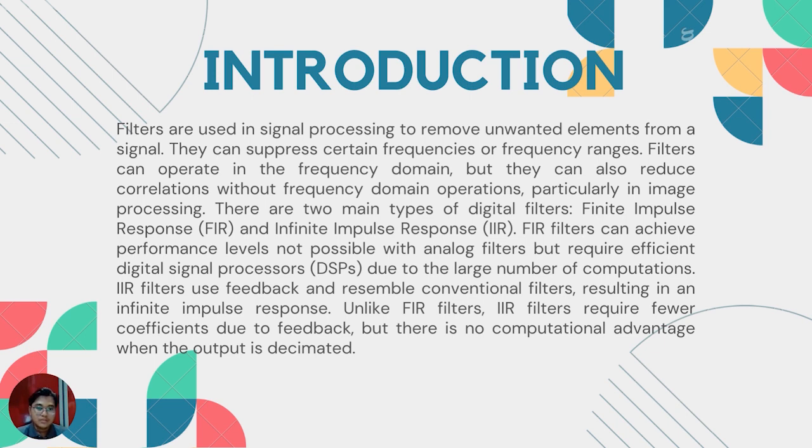IIR filters use feedback and resemble conventional filters, resulting in an infinite impulse response. Unlike FIR filters, IIR filters require fewer coefficients due to feedback, but there is no computational advantage when the output is decimated.